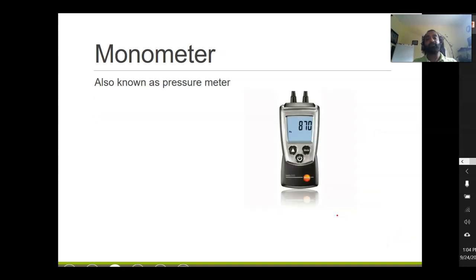A manometer is a piece of equipment that we use to measure the pressure, and probably you will use that on a duct system to detect leaks. Again, we can measure air velocity, and we know about pressure leaks with air pressure. I mean, if you want to know if your car tire is leaking, you will inflate it, and you go with soap and water and look where the bubbles are forming, right?